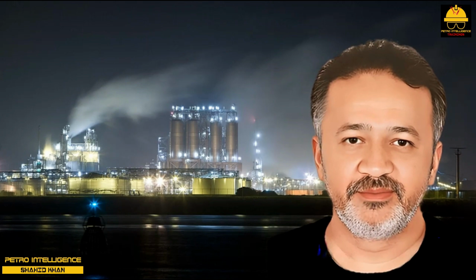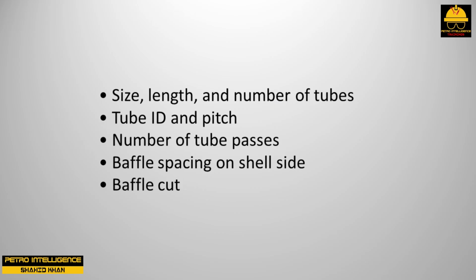Specify yourself. Size, length, and number of tubes. Tube ID and pitch. Number of tube passes. Baffle spacing on shell side. Baffle cut, then, you will get the exchangers you really want every time.